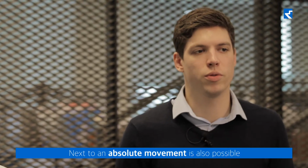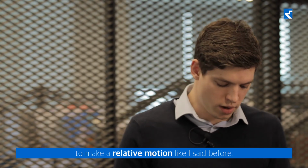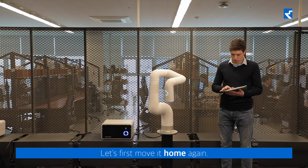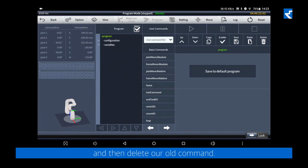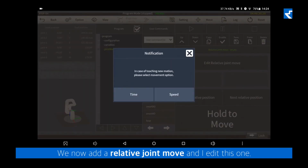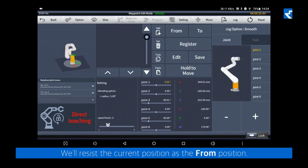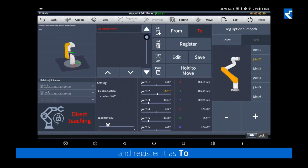Next to an absolute movement, it's also possible to make a relative motion, like I said before. Let's first move it home again and the delete or alt command. We now add a relative joint move and edit this one. We'll register the current position as the from position. Then, let's move around the robot a little and register it as 2.